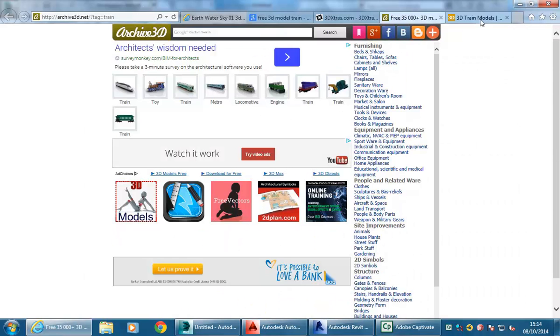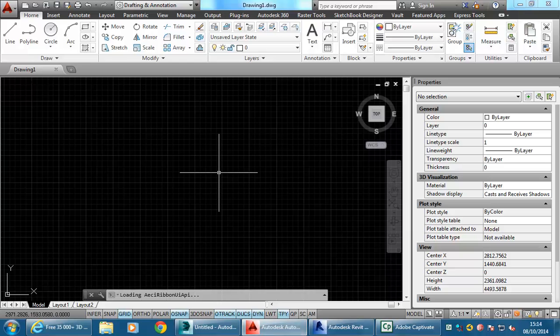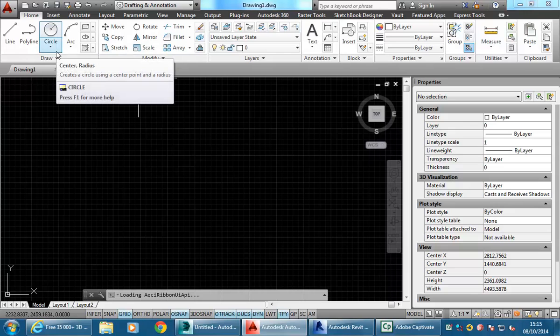And then, finally, AutoCAD can be a good option as well. So if you've got complex designs, especially in the plan layout, sometimes it's just too much work to try and set them out in Revit. And so especially things like complex stairs, I know a lot of you might be thinking of curving stairs that don't follow a straight or just an arc type path, and setting those out in Revit is a huge amount of work. So what you can do then instead is do some of the plan layout in AutoCAD and still